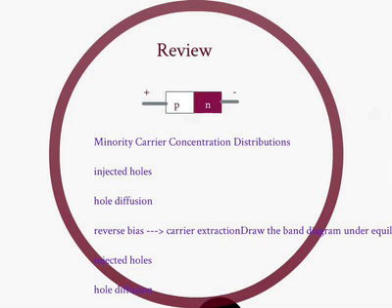So our goal is to be able to quantitatively calculate the collector current as a function of some bias voltages. What's going on here is that you have a majority carrier injection. Then those majority carriers become minority carriers in here, and they diffuse and recombine. So you have a diffusion equation here, which is exactly the same as the forward bias injection we did before. So that's the logic we will apply.